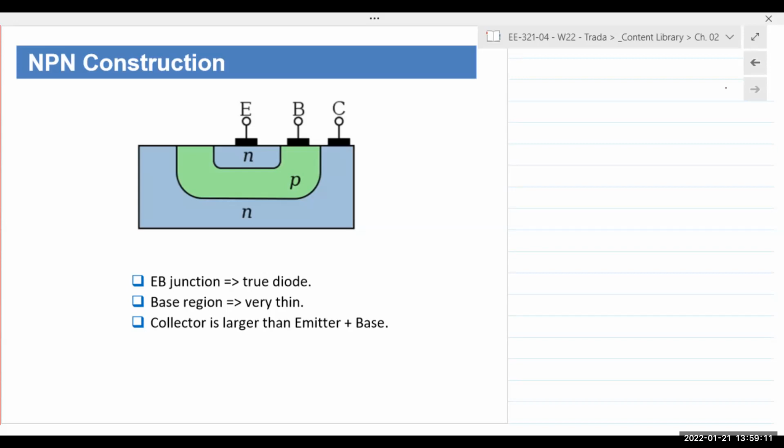And so for a transistor, this one is an NPN, so you have an N-type silicon wafer. You open up a hole in there, and then you insert P-type material. Once the P-type material goes in there, you have one PN junction. Now you open up a second, smaller hole inside the big one, and you insert another N-type material from the top. And that's why the base is kind of encapsulating the emitter, and the collector is encapsulating everything. Does that make sense?